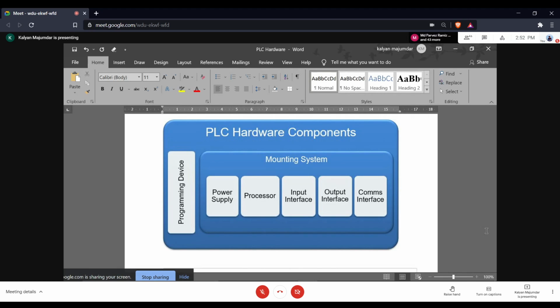And similarly, you have analog outputs. For example, say you want to drive a control valve that you have studied. Control valve position can change from 0 to 100%. It is a continuous variable. You know that you have a 4 to 20 milliampere signal coming out of a controller that's converted into a pneumatic signal, and that finally operates a valve. So here you require an analog output.